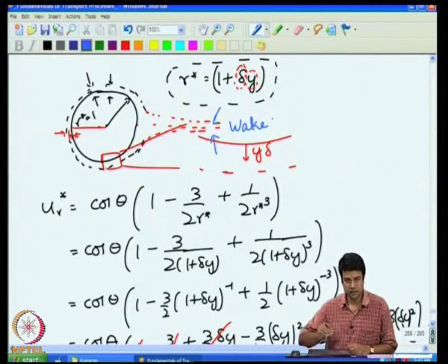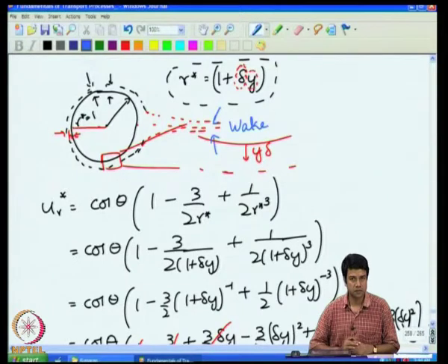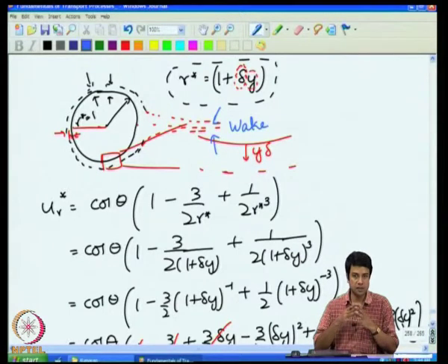Downstream of the sphere there is convection downstream. Therefore, the effect of the velocity, the velocity for the stagnation streamline, both upstream and downstream are identically equal to 0. And because of that, there is a diffusive effect downstream of the sphere, which gets reflected in a long wake as you go downstream. Our analysis of the boundary layer thickness has only told us so far that the wake exists. It does not tell us any details about the temperature within the wake, and that is because I have explicitly assumed that delta is small compared to 1 when I did the boundary layer analysis, and therefore, I require that eta, which was y by h of theta, has to be order 1. If h of theta becomes large, then that condition is no longer satisfied, and I cannot use the analysis that I have been using so far.